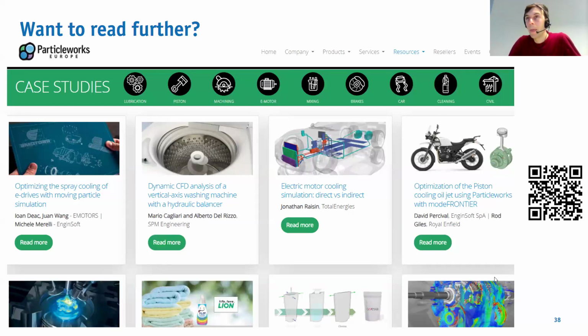Omar asks about the comparison, the greatest advantages between Particleworks and other CFD solutions. As mentioned, whenever we have complex geometries, splashing, jets, oil jets, spraying phenomena, so free surface flow, multi-phase flow, we have a method here that is much easier to set up and also guaranteed to be stable in the solution as compared to traditional CFD. So I would say that one is the main advantage.